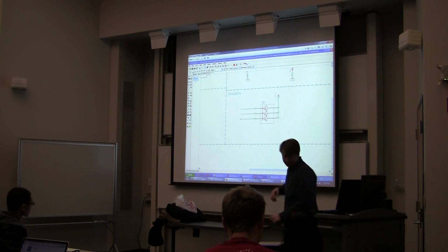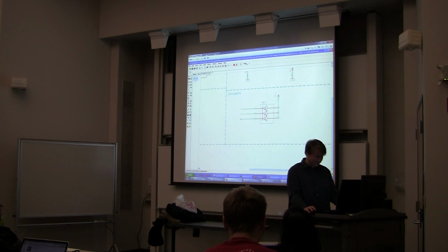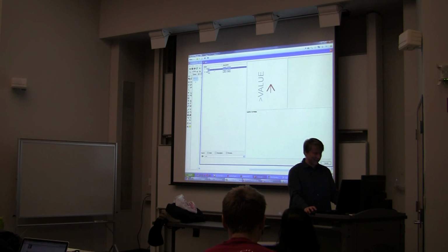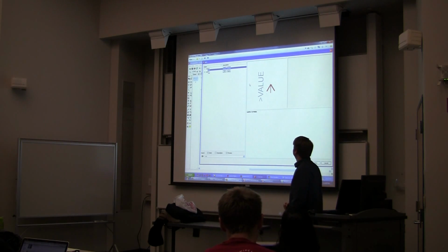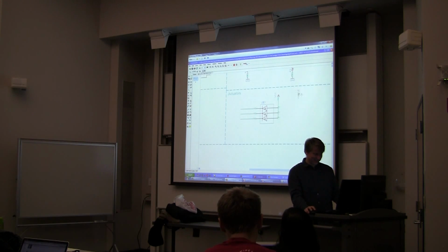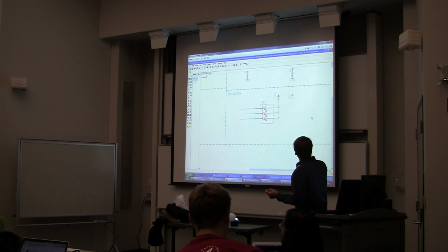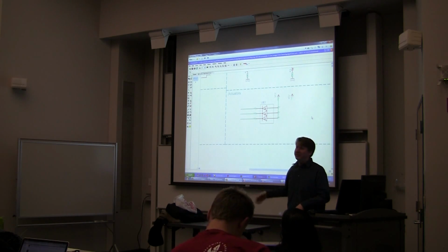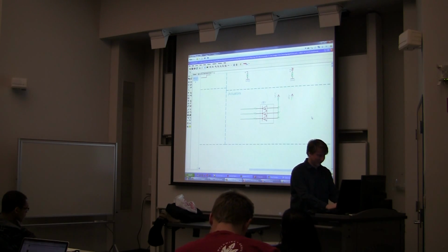You could also, if you really wanted to, add 5V. There's all kinds. Like if you said, I'm using 5 volts, I'm going to use plus 5V, that's going to be my supply. You know, down it comes. You just want to make sure you use them. You don't want to just rename them because that doesn't actually do anything.